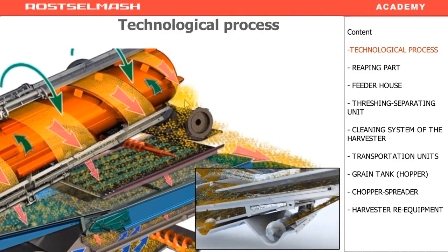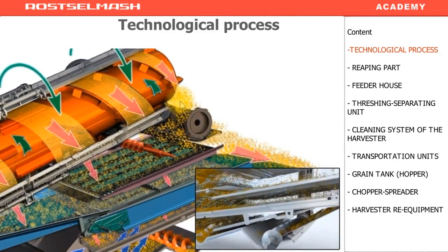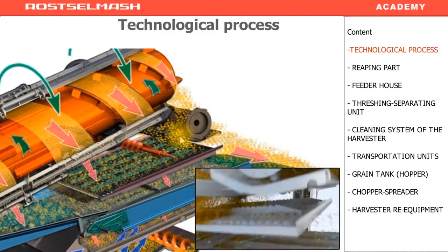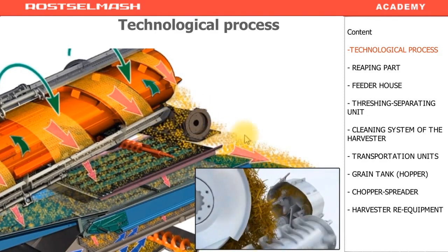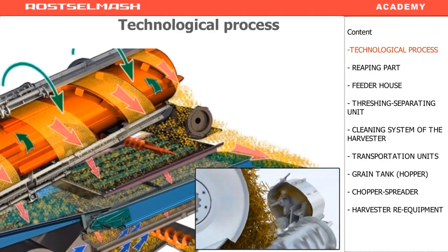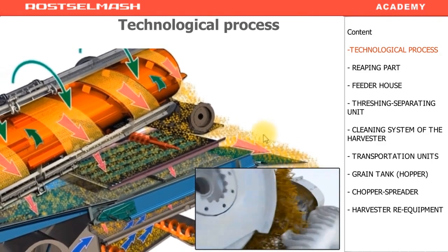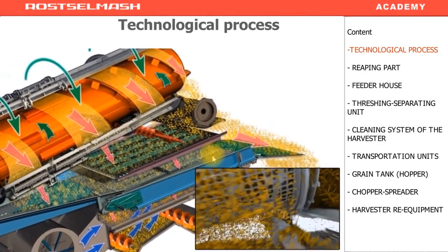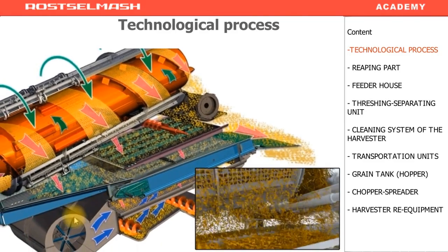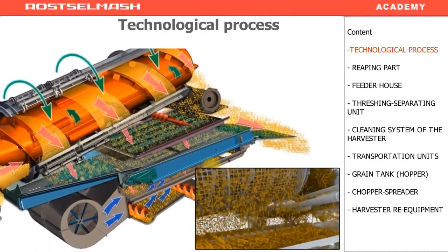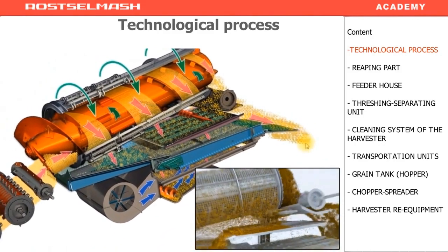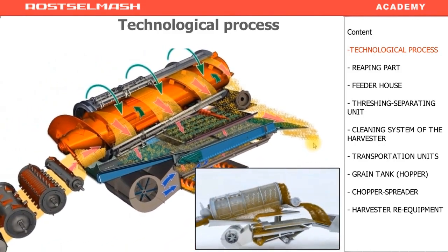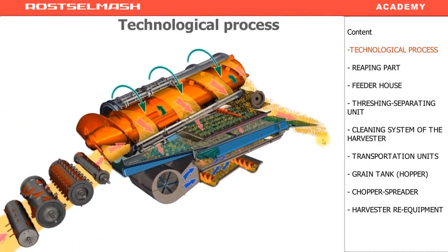At the end of the rotor, we have a straw output. The straw is moved down, and with the help of a straw beater, is forced out of the combine. Small particles and chaff, which are blown by the fan, are also moved here. Eventually, all this mass flow is spread on the field, if the chopper is in the windrower mode.